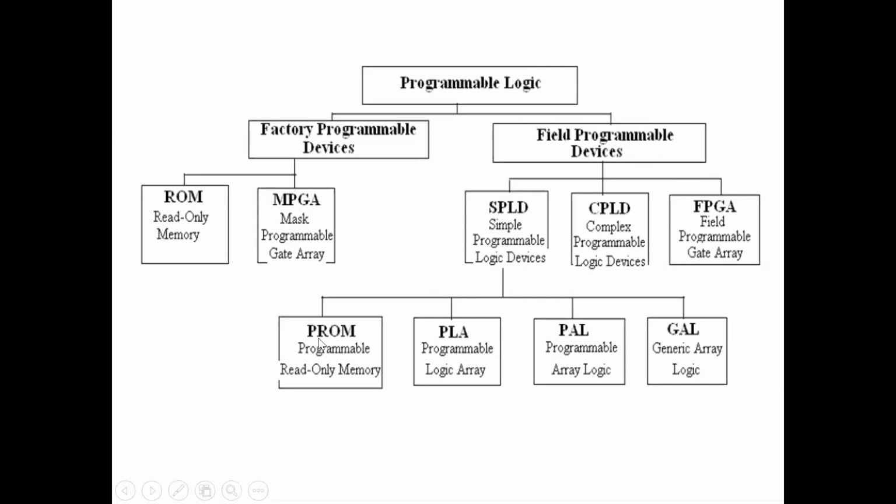Under simple programmable logic device, you have PROM, programmable read-only memory. Here, read-only memory is permanent. Programmable read-only memory is you can program it according to your application. Then programmable logic array, programmable array logic, and the generic array logic. The generic array logic family consists of electrically erasable programmable devices designed using Lattice Semiconductors. Actually, it is similar to a PLA, but it can be reprogrammed and it can also be erased.